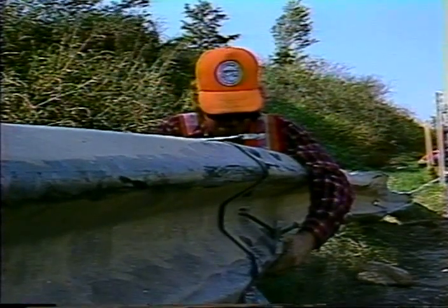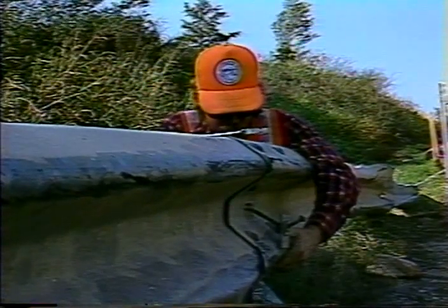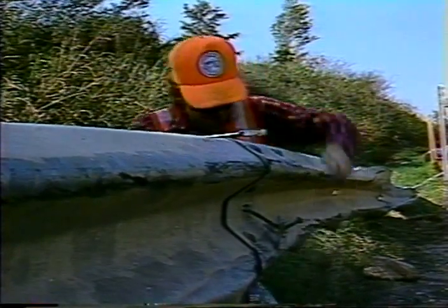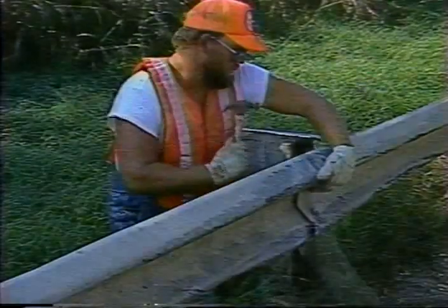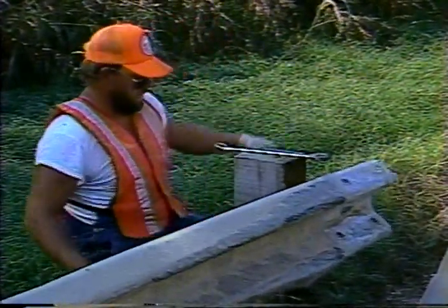After the nuts are taken off, the damaged guardrail can be removed. Care must be used at this point. Kinked or bent guardrail must be cautiously removed. Railing that is distorted with bows or kinks can build up a lot of internal tension. When the railing is pulled free, it can spring back and injure someone.